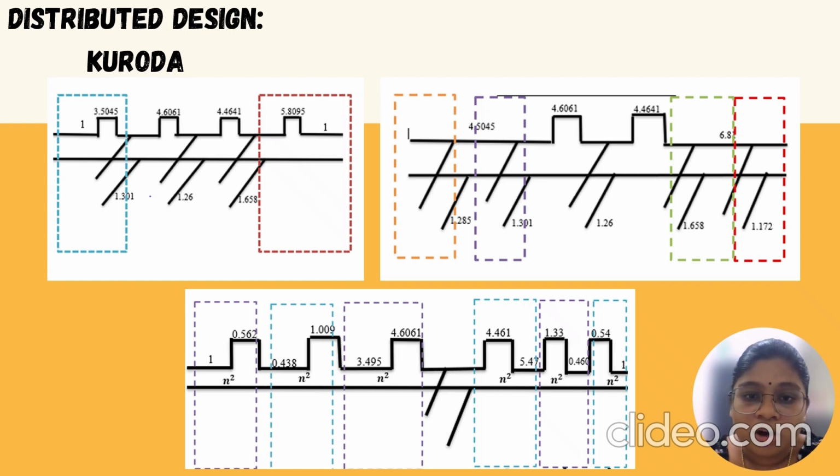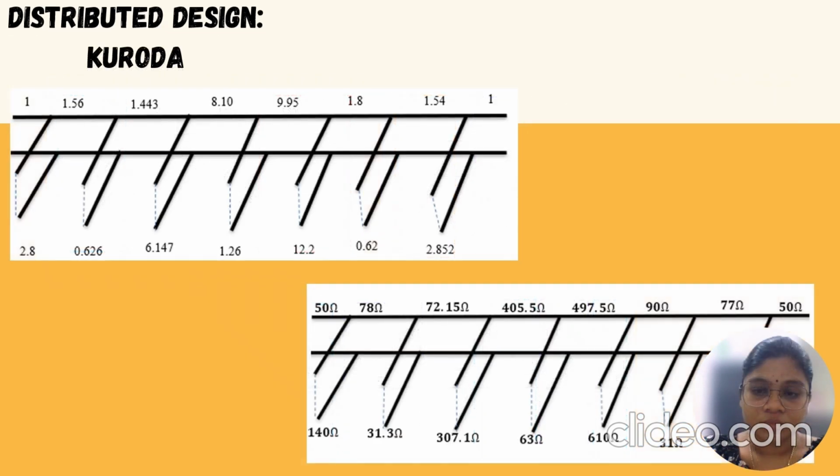So these four highlighted boxes I want to change from open circuit to short circuit. So the final practical layer, after all Kuroda transformations have been applied, here all elements are realizable, shunt configuration, and impedance inverters as scaling factors. So the transformer is used to maintain the same filter response while ensuring all sections have practical line width and specific spacings. So this approach makes the distributed low-pass filter design practical for implementation on a microstrip or stripline circuit while maintaining the desired frequency response characteristic.